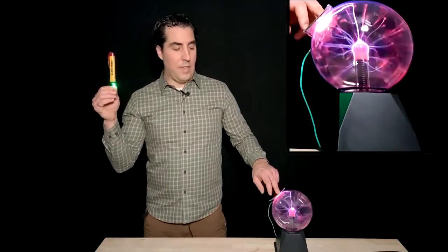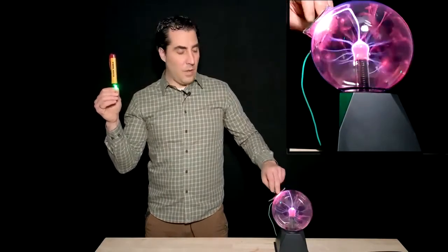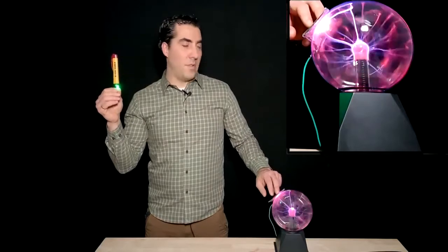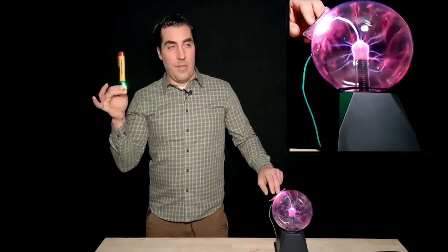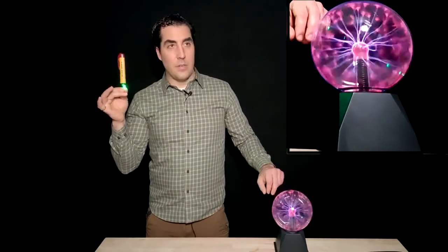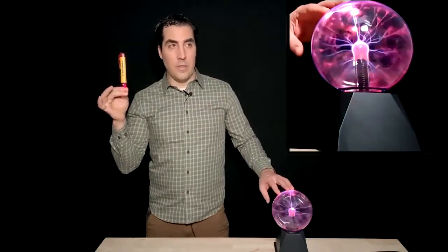So the electric field attaches onto the metal foil and goes through the ground cord to the third prong without inducing a voltage onto myself. Now, if I drop this little foil that's grounded and touch it again, there's a voltage induced.